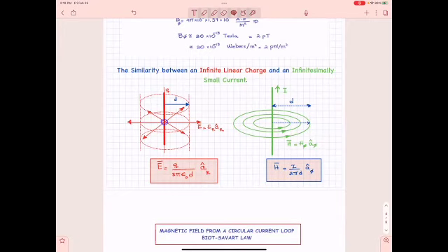And it has not the R component, but it has the phi component. Remember, the phi component goes exactly as you see here, like this. That's a phi component in the cylindrical coordinate system. You remember that? And this phi component of the field is given by I, which is the current, divided by 2 pi d. So it also changes as 1 over d.